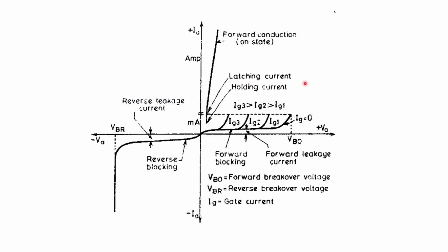properly turned off. Okay, so these are a few current parameters, and some additional current parameters are the I square T rating, which is the minimum fuse rating required for the thyristor protection. And some ratings such as di/dt rating, the maximum di/dt allowed through a thyristor. So we understood what is the voltage rating and what are the current ratings of the thyristor.